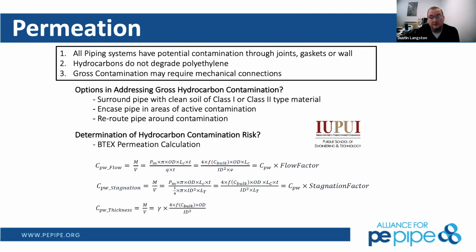Very similar to what you would use for a ductile iron pipeline using a polyethylene pipe wrap, you could use a nylon pipe wrap for polyethylene, or any bell and spigot jointed pipe for that matter, to make sure that you don't get that hydrocarbon permeation into gaskets or pipe. So Dusty, is it true that they use polyethylene to wrap ductile iron? Yeah, yes, it is. They're Bio V Max, or I can't remember their product.